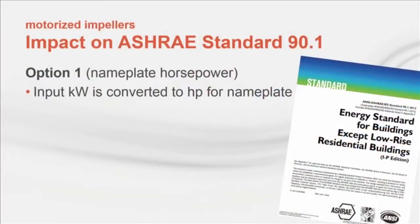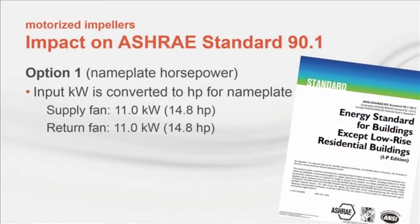In our previous example, the input power to the supply fan array was 11 kW, and also 11 kW to the return fan array. So the total horsepower on the nameplate would be 14.8 for each array. Keep in mind that this value includes variable speed drive and motor losses, so you might have a higher nameplate horsepower when using a motorized impeller compared to a traditional direct drive plenum fan. However, it could be lower if the direct drive plenum fan had to jump up to the next higher NEMA horsepower increment, from 7.5 to 10 horsepower, for example.